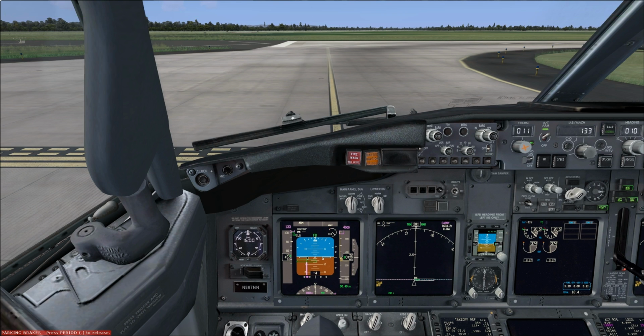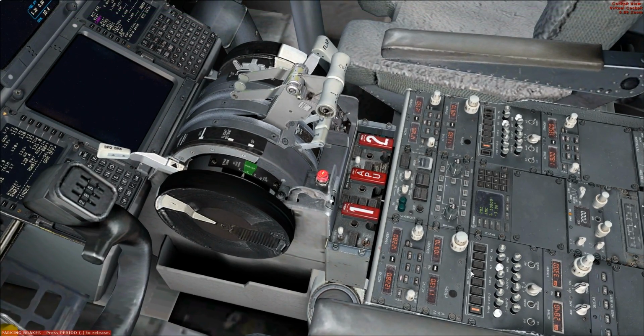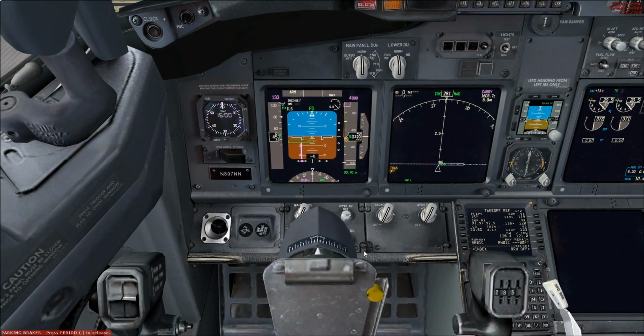Now, if you own the PMDG 737 or the 777 along with Activesky Next, then you have the ability to produce a microburst on your own with Activesky Next and detect the microburst with the PMDG aircraft. The PMDG aircraft simulates the Collins weather radar system. It's only on the 737 and the 777, and this system comes with what's known as a predictive wind shear system.